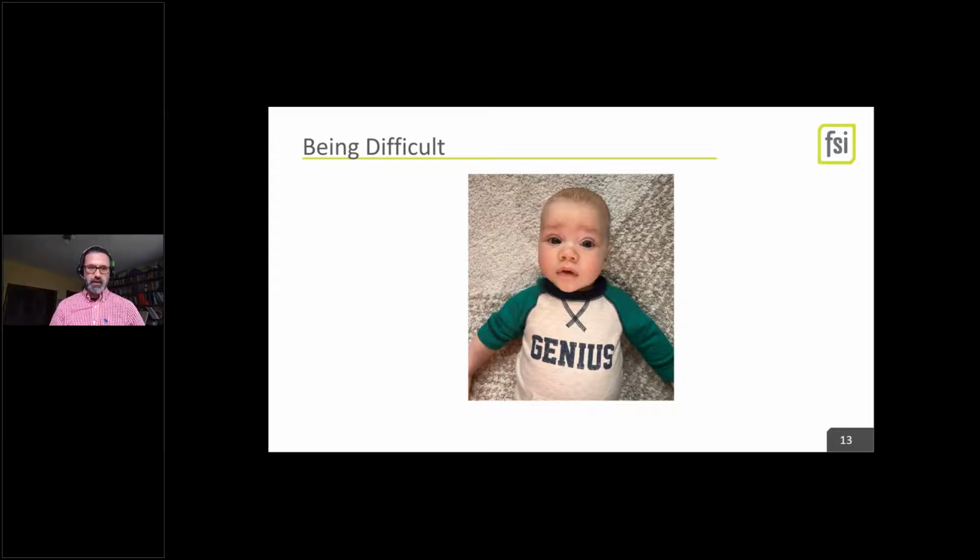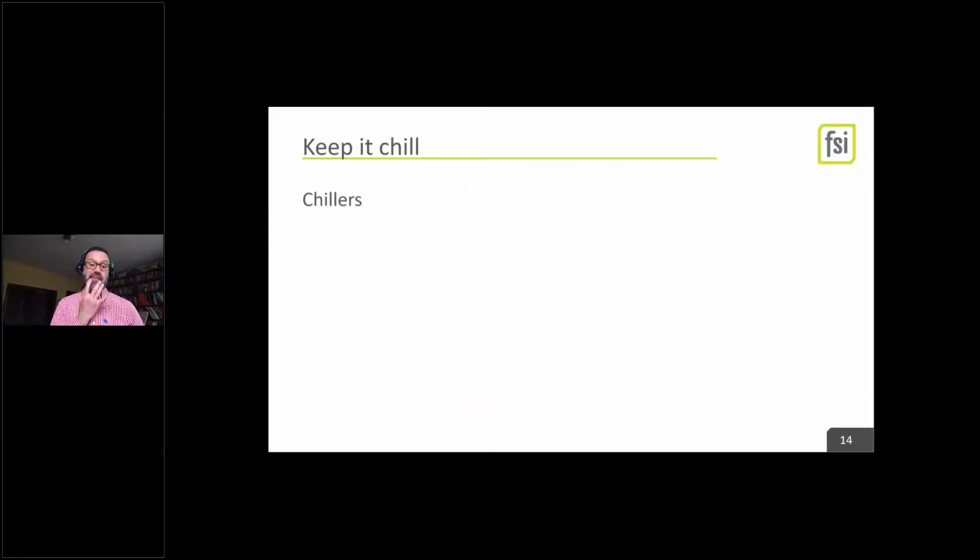Perfect. All right, so I'm going to start with easy. Easy is nice. So chillers, if you're replacing your chiller, it's electric already, although I did see a natural gas powered chiller and was kind of aghast at that. So it's pretty easy. You need to meet the new efficiency values. Heat recovery chillers don't have industry standard ratings yet, so that's a bit of an interesting one, although the industry is kind of coalescing around specific efficiencies.